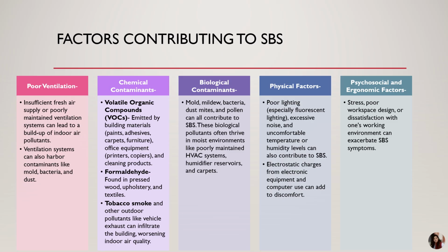So a factor that can contribute is if we are not providing a proper, sufficient air supply, and it is leading to a build up of indoor pollutants. At that time it will harbor many molds, bacteria, and dust. Volatile organic compounds, that is VOC, emit a lot of chemicals from paints, adhesives, carpets, furniture, office equipment, printers, and cleaning products, formaldehyde present in wood, textiles, use of tobacco, vehicle exhaust, all these things are called chemical contaminants.